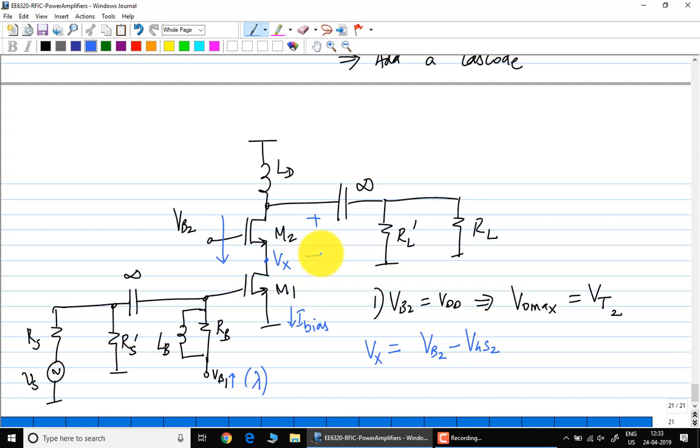The minute you do this, you can imagine the amounts of capacitance. You are dealing with picofarads of capacitance everywhere. Now you see why CGD is a problem. CGD is probably going to be like 200, 300 femtofarads, half a picofarad. These kind of CGDs you would never have dealt with. It can easily become unstable.